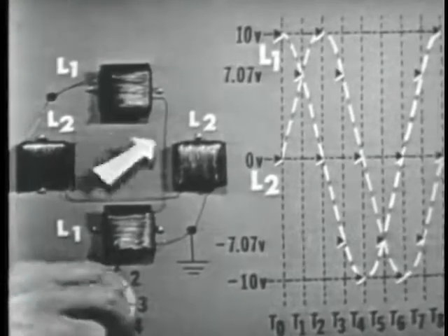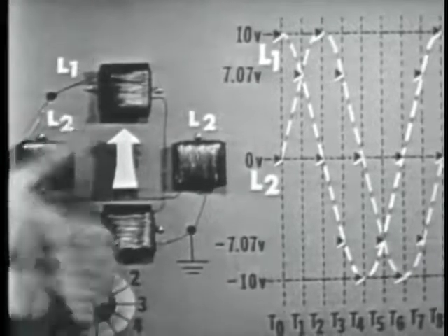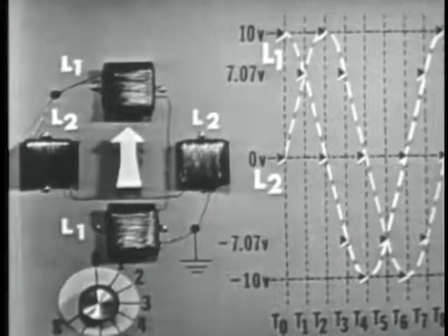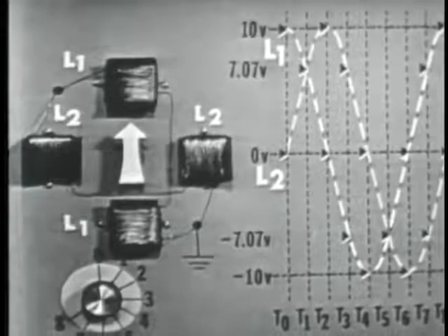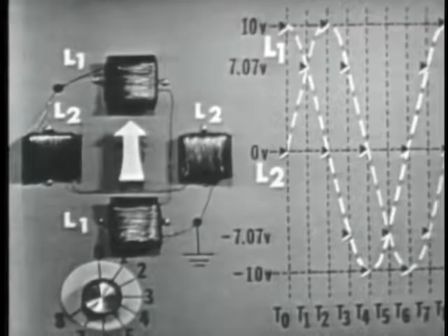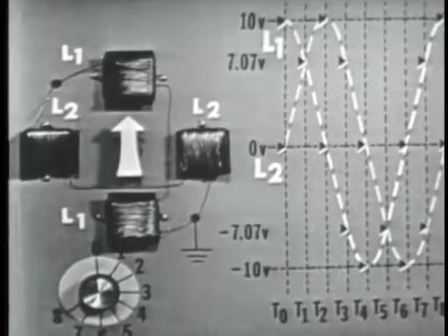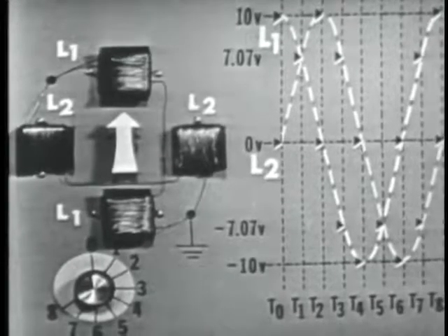And, by the way, we might point out, Tom, once again, that you can apply the left-hand rule to all these coils and prove precisely what we've said, right? We can develop a rotating magnetic field. I'm certainly glad you said that, a rotating magnetic field that induces a voltage in the rotor, causing it to become an electromagnet, which will follow the rotating magnetic field.